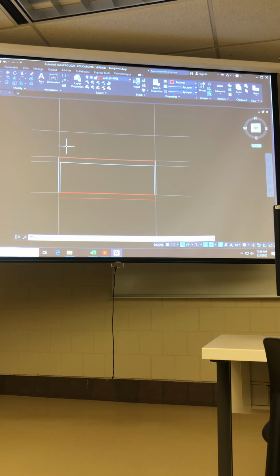So I'm going to go ahead, go back to my drawing, and I am going to extend 1 foot 11 inches to the outside face of my exterior wall or truss, and that's where the tail of my truss ends. And I'm just going to extend my top chord lines to meet that, and then go ahead and do a bunch of trimming.